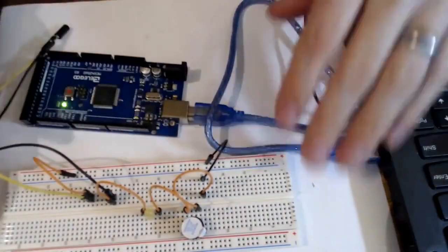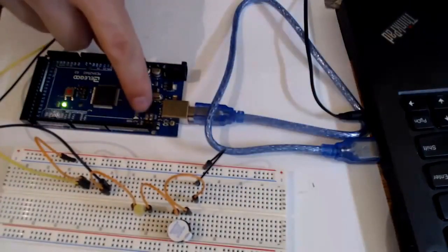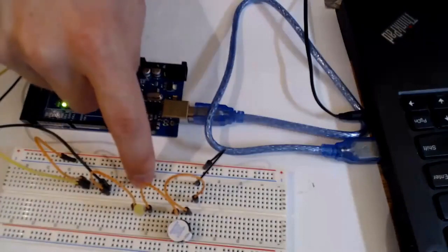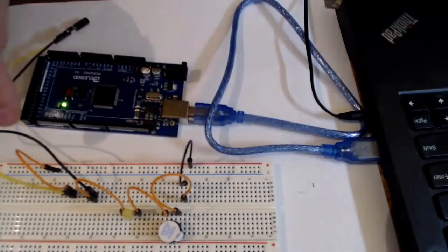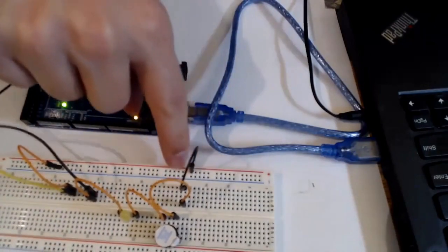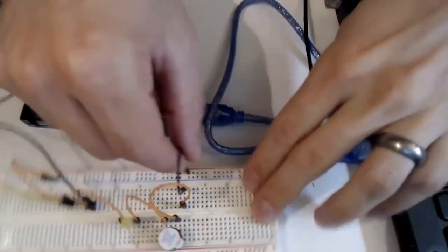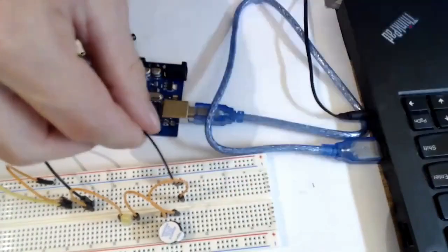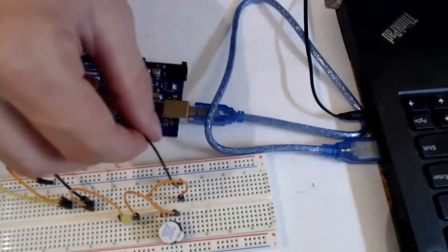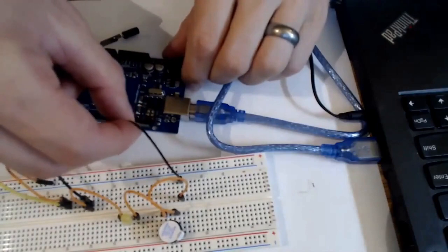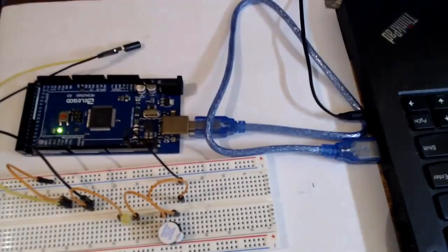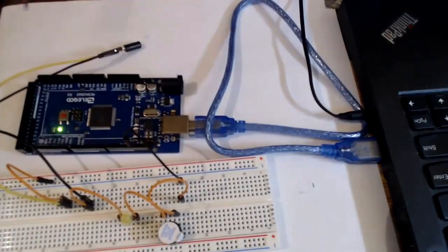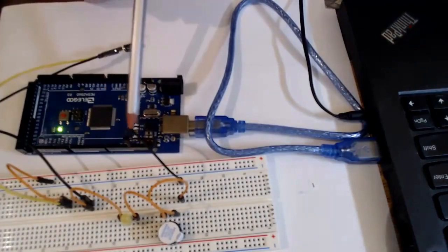Now, there's just one or two small changes that you can make so that instead of powering this little onboard LED, it's going to power this entire circuit. Previously, on the positive rail, I had this jumper. I'm going to take that out. And instead of going to the positive rail of the breadboard, I'm going to put it into pin 13 on the Arduino. It's a little hard to see, but these are much easier to see in person. The little push pin just went into the number 13 right here.